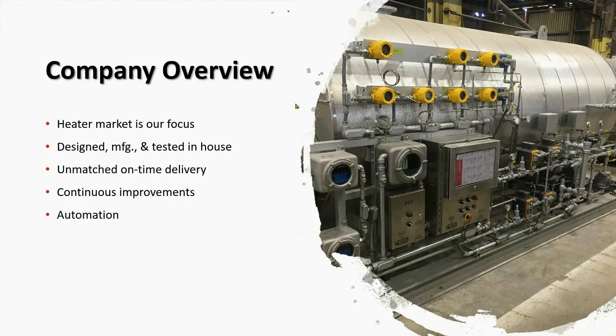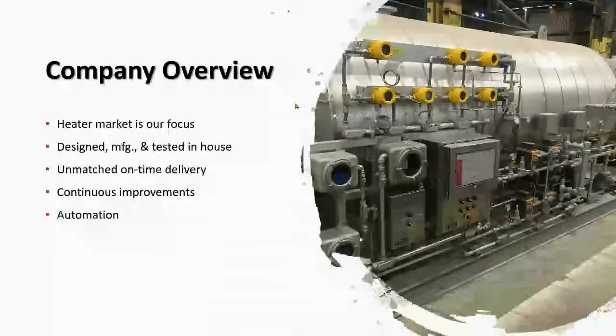And also in the shop, we have implemented automation with automated welders. These have allowed us to reduce production time on the large horizontal seam welds on the shells or the end plates of the heaters, in some cases from days to hours, and also allowed us to maintain a consistent weld quality, since there's not a variation between welding operators. Of course, we do have code welders on staff that are responsible for welding the high pressure process coil.